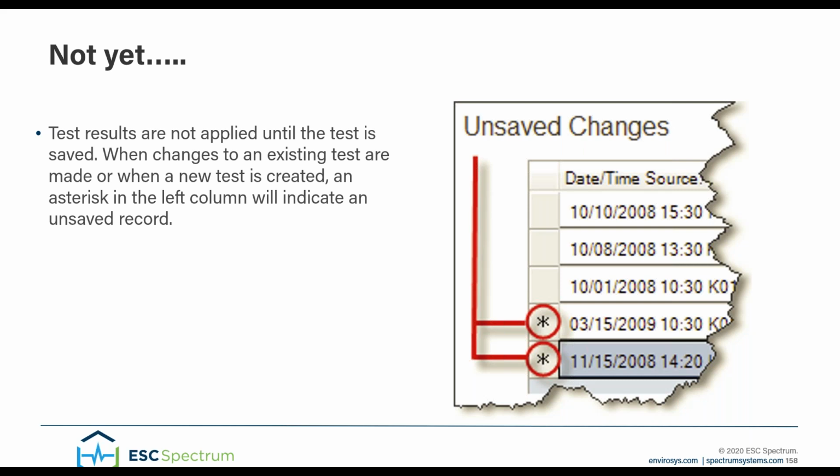Now, if you've put the information in and maybe you've picked the wrong parts or pieces and it doesn't look like it's going to work for your purpose, you can just exit out of it, don't save anything, and then just come back in and start again. And that's easy to do. Maybe you've selected the wrong instances or the wrong parameter. Just cancel it out, come back in, and do it again. Because remember, nothing is committed to the database until we click Save.